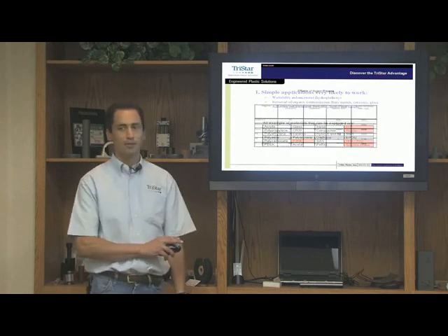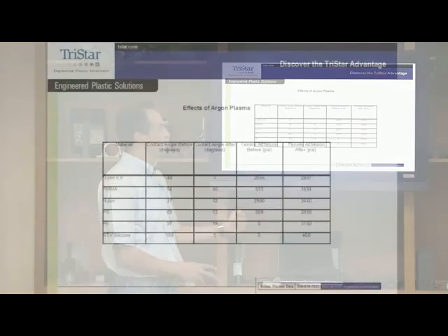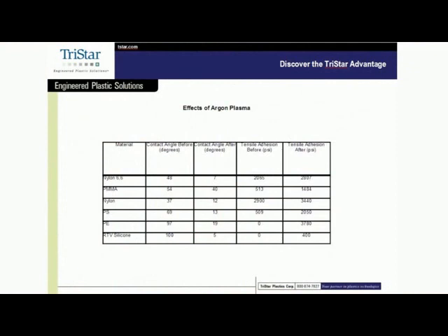When I say it works, what does that mean? In simple adhesion terms, there are some common polymers listed here, and at the very end is, after plasma treatment, after they're bonded, what type of increase of adhesion are we looking at? Some of the increases in adhesion are marginal, while some are dramatic. A marginal increase would be nylon 6,6. Nylon 6,6 in its own conformation has a tensile lap shear of around 2,000. After plasma treatment, it goes up to 2,800. Not bad, not good, it's okay.